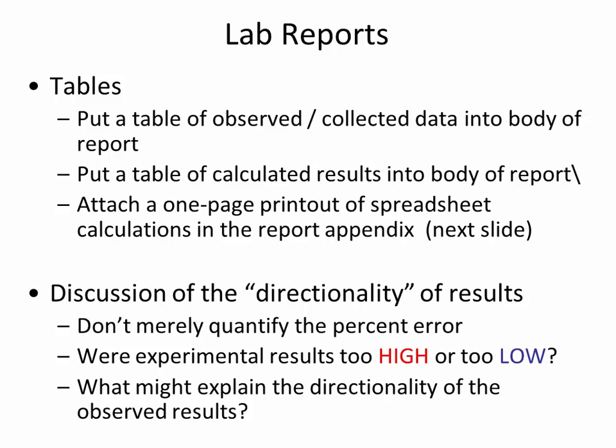I have good confidence in this formula that's predicting the theoretical C sub D. The average should have been 0.77, but the average was 0.73. So on average, the experimental C sub D is less. So why would it be less? I need to explain in my discussion why my experimentally observed discharge coefficient is too low.